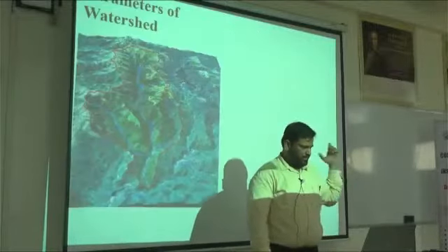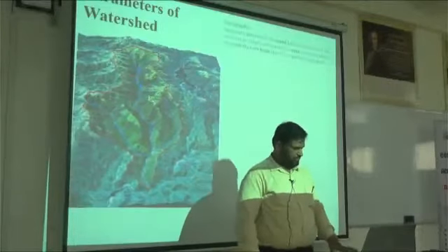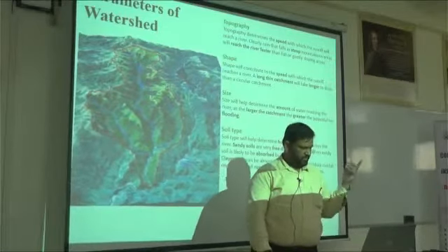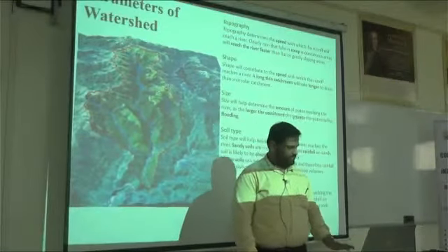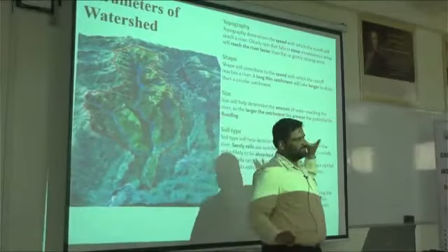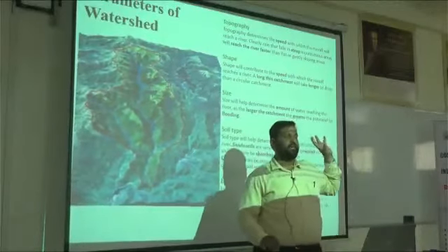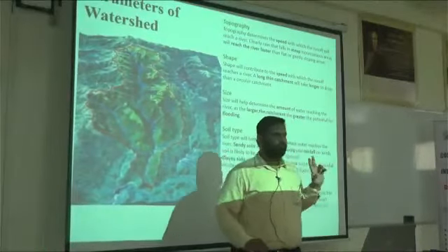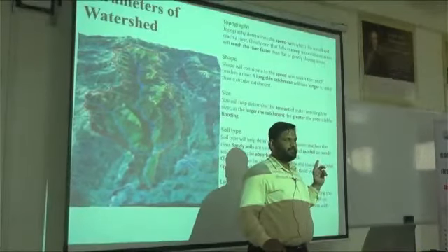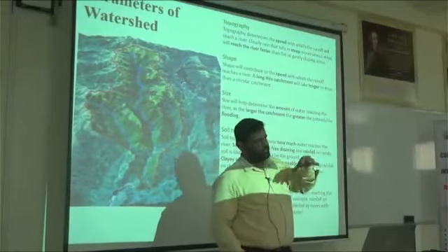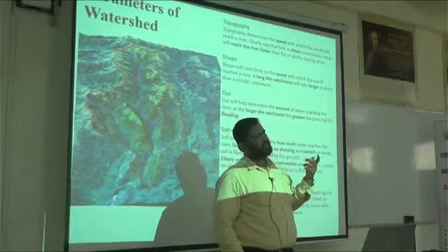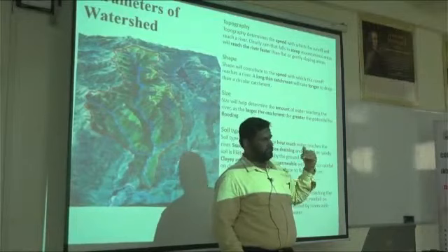And while doing these types of studies, we should know some catchment characteristics, like the topography, the shape of the catchment, the size of the catchment, then the land use of the catchment. Why? Because they all govern the runoff characteristics, as well as the runoff volume. How would topography govern the runoff characteristics? Because wherever you get a steep slope, you will get more runoff generation, and the lag time, your time of concentration, would be less.